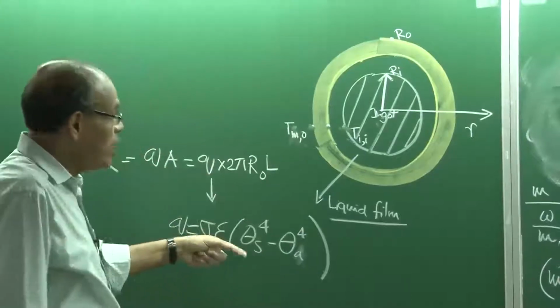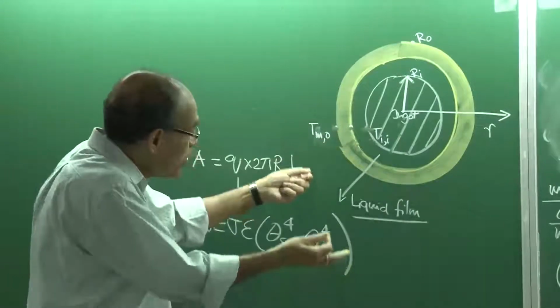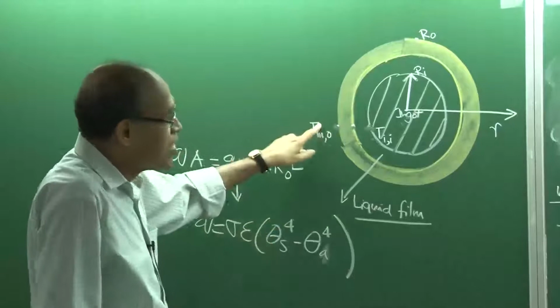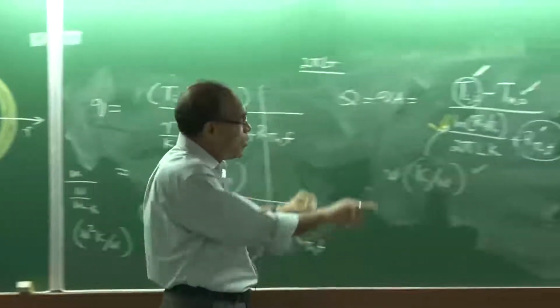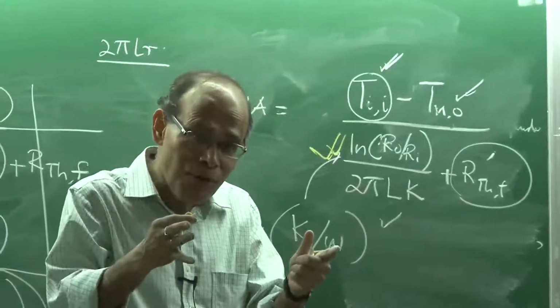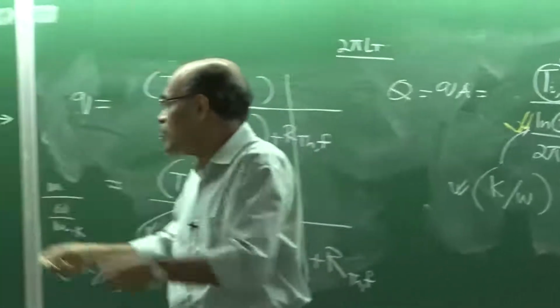This of course is going to be time dependent, but at the instant when the mold is withdrawn, if you have a fixed temperature, we should have a fixed heat flux, and we can find out this, which will correspond to the resistance offered by the film at the instant when the ingot is being stripped.